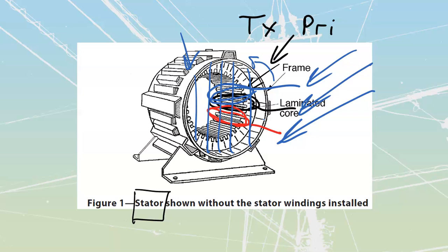If I've got dust or anything like that, or corrosives, or anything that is going to be granular, that's going to grind it down, I might not want to have that open type of machine. I'd probably want to have a closed type of machine. Inside of your binders over here, they go through a whole pile of different types of enclosures.